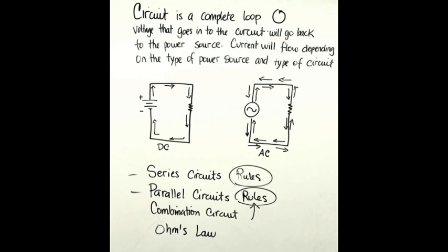I can't use formula number 2 because I actually have 3 resistors. So here I'm going to use formula number 3 to get the total resistance. So this is my voltage total. This is the pressure being applied to the circuit. Now here I'm going to put R total equals 1 over 1 divided by 5 plus 1 divided by 20 plus 1 divided by 4.